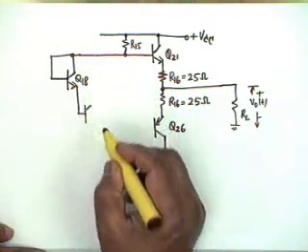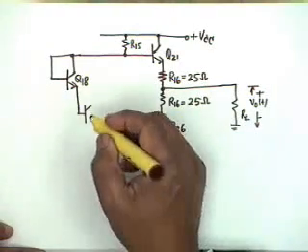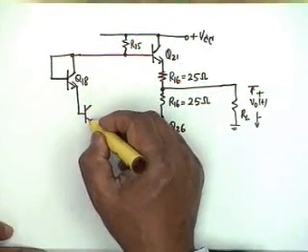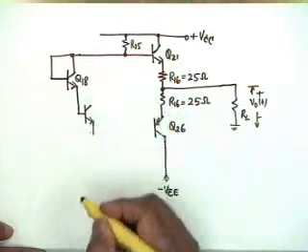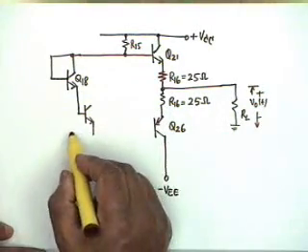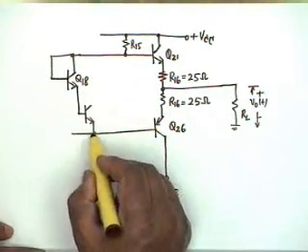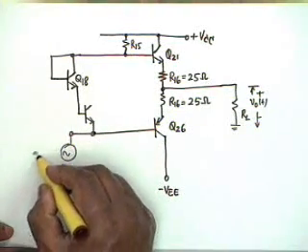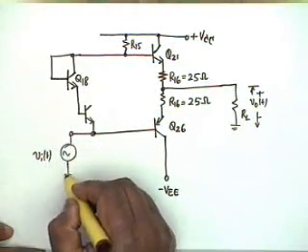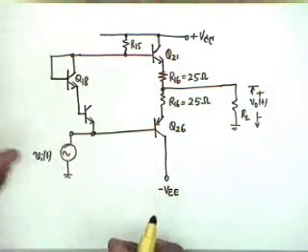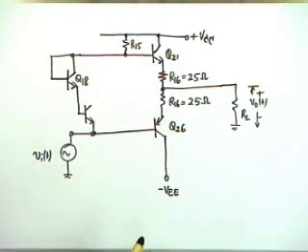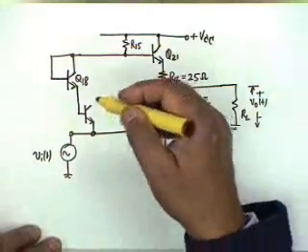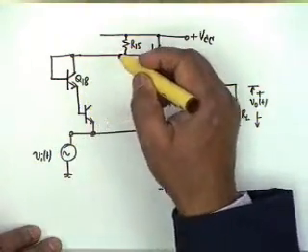Then we require another such diode connected transistor, but for reasons of the overall mu A 725 design, it is connected like this. It is not connected as a diode, it is connected like this. This is VIT, the input from the previous stage. The previous stage could be a differential amplifier. Okay, and instead of getting this connected as a diode, this is connected like this.